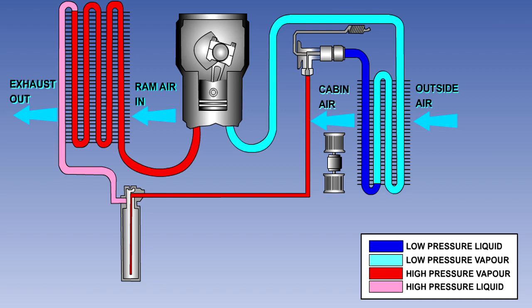The vapor cycle air conditioning system is similar in operation to the domestic refrigerator, or the galley cart cooling system used on some large aircraft. Its use for aircraft is now generally limited to small piston engine types. The system uses a refrigerant, normally Freon, which alternates between the vapor and liquid states.